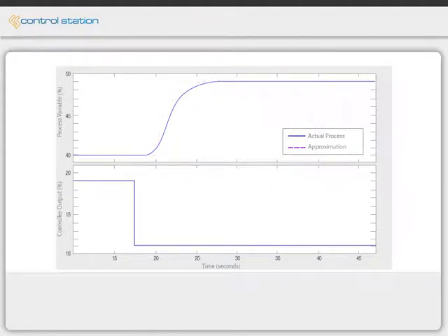Recall that dead time is the time delay that passes from when the controller output step is made, until when the model shows its first clear response to that action, regardless of the process gain and/or time constant values. On your screen we compute and display the FOPDT model response with an increased dead time. As the plot shows, increasing dead time simply shifts the approximated model response curve without changing its shape in any fashion. A larger dead time means a longer delay before the response first begins.